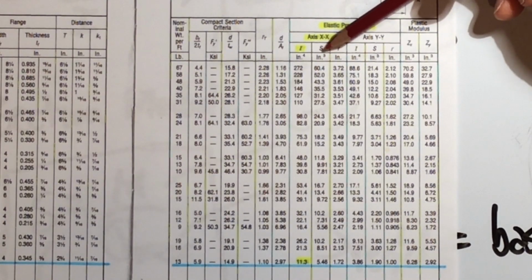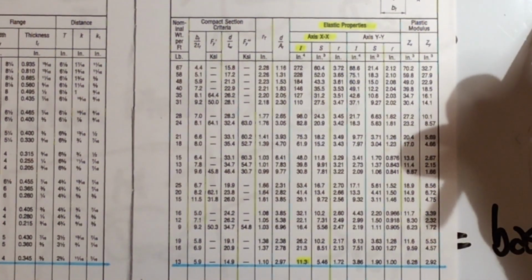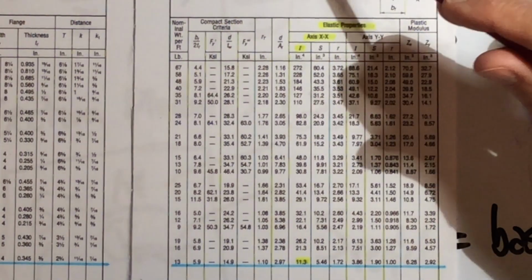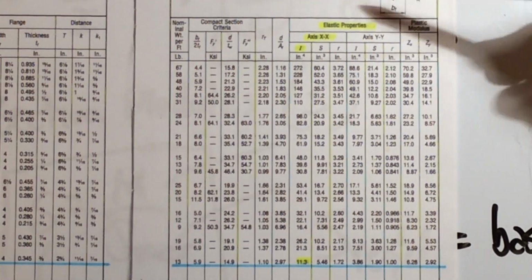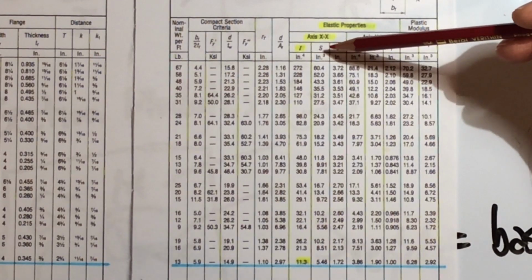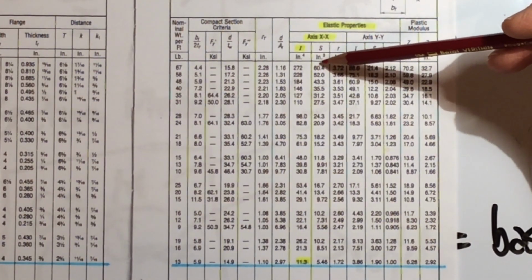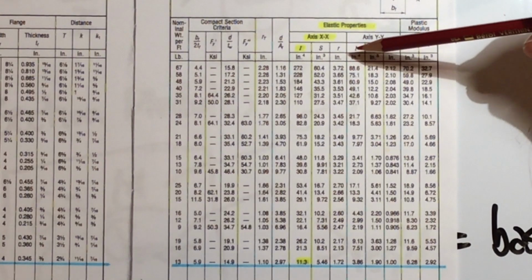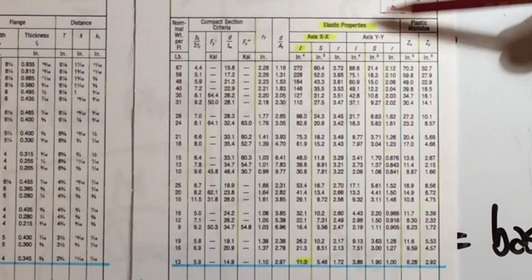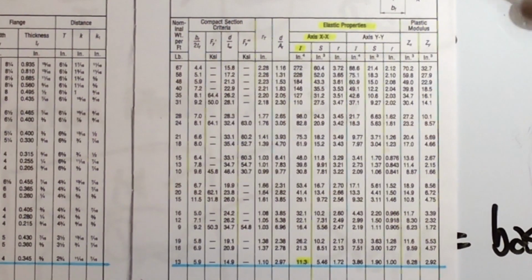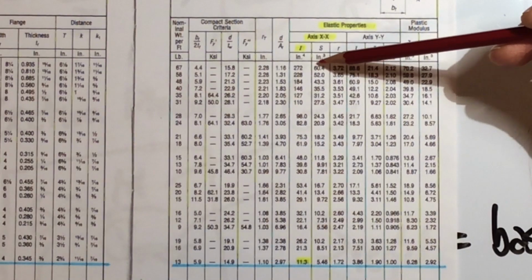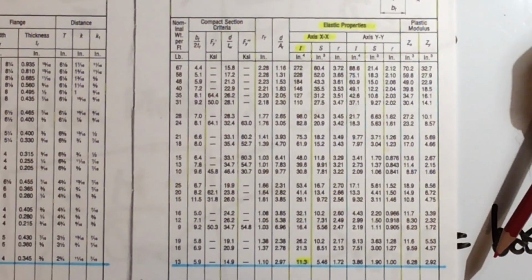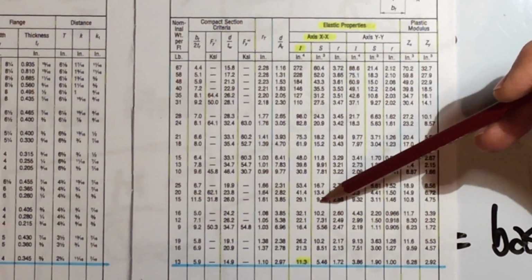So in other words, if you found a beam based upon the steel sigma max and its maximum moment that you calculated based on a shear moment diagram, and plug that in, all right, you're going to get an S required. And then all you have to do is come through here and look at all these different shapes. Again, wide flange, channels, angles, rectangular, whatever, and start looking for values in excess of that required S value, and then you would choose that beam. All right, you would choose that beam based on these values.